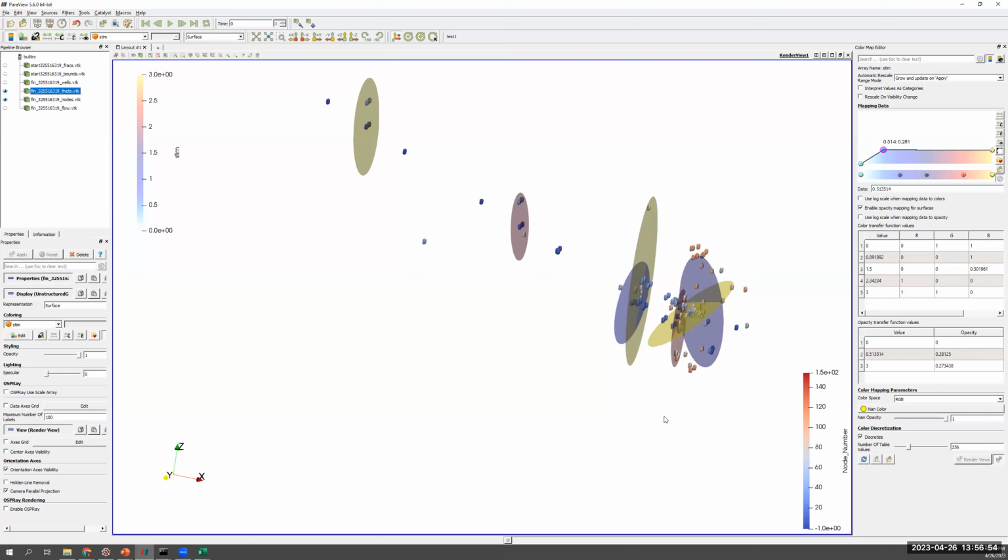In this case, GeoDT is kind of like the opposite. It's designed to simplify a lot of the numerical solution down, but still retain the ability to answer questions that we care about from an engineering perspective, rather than the details of the XYZ coordinates within the space. Hopefully I'm saying that in an effective way. But another way to phrase this is you can use GeoDT as kind of like your first cut to figure out what parameters you might want to use if you then want to proceed with more high fidelity modeling using tools like DFNworks.